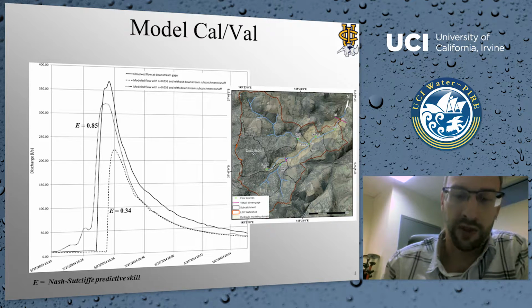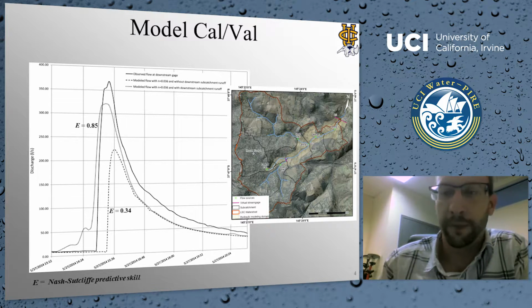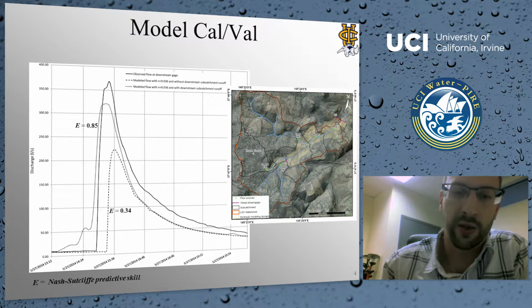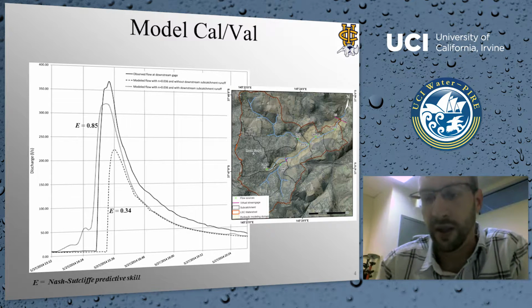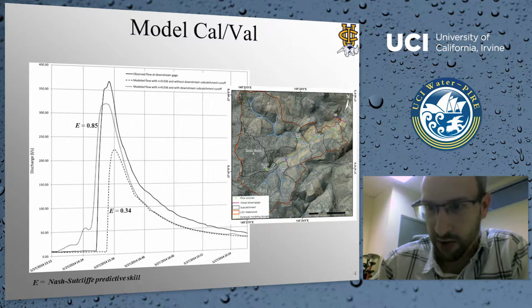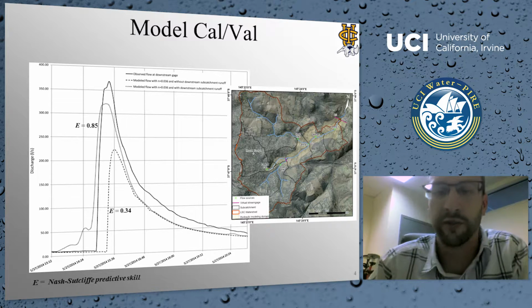We could not improve the predictive skill of our model until we realized that by injecting the flow only at the locations where we were measuring the flow for this event, we were under-modeling the runoff into the catchment from any subcatchments downstream of those gauges. So I had Matt run his hydrologic model for this particular event and compute the runoff for all the downstream subcatchments, which we then injected into the model at the locations marked lateral 1 all the way up to lateral 3.